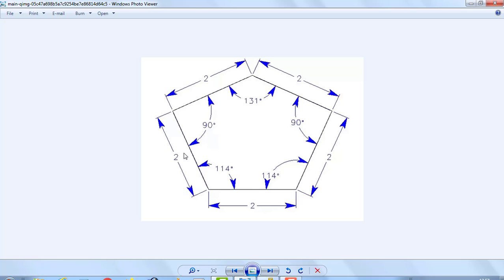Click on yes. So here we have created this A point and the B1 point, and now we are going to create this C point. In order to create the C point we have to use the point in direction option, in which we can give the angle. While using the point in direction option, whenever it asks us for the from point we need to select this B point. We don't want to select this A point, because this line will be created from the B point only. So for that we need to select this B point as the from point, and the 2 point we need to select this A point. So let me show you.